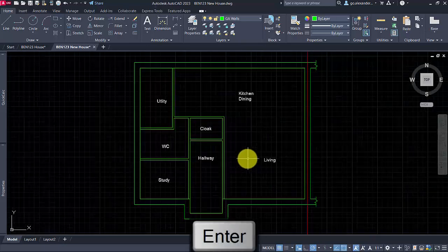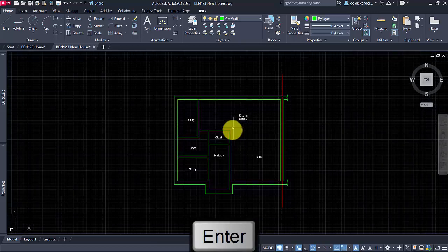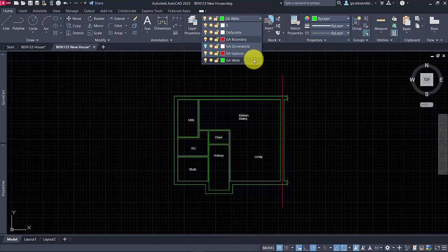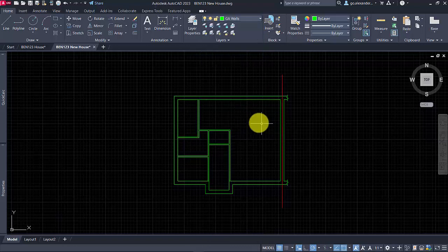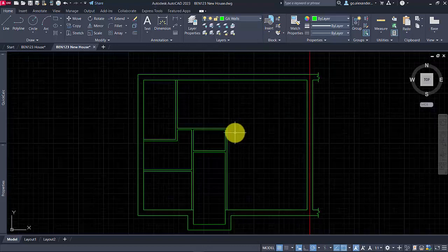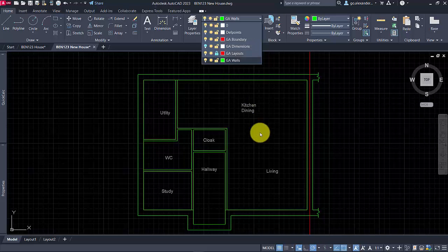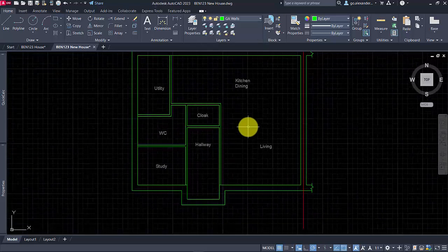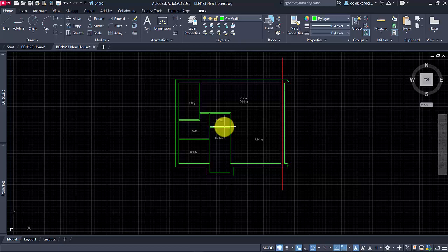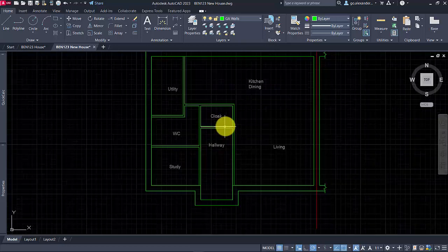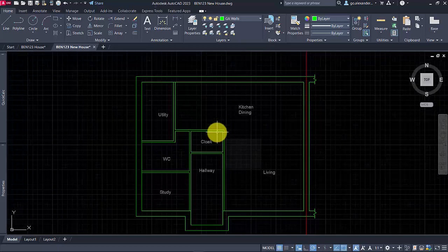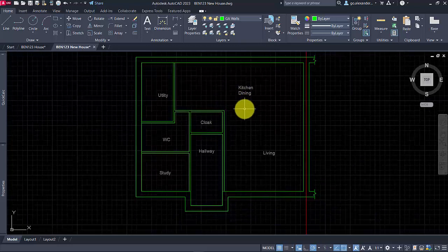So that's all the internal walls I've traced over, but as I said, sometimes those may or may not come up accurately. At this stage, we can actually turn off the layouts layer. Unfortunately, that has hidden the room names in this case, but what we could do is leave the layer on and we can lock it so that it doesn't get edited as we are fixing and moving around with the next stage. So you do need to replicate that also for the first floor.